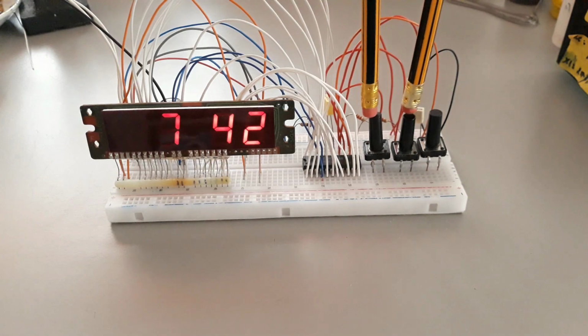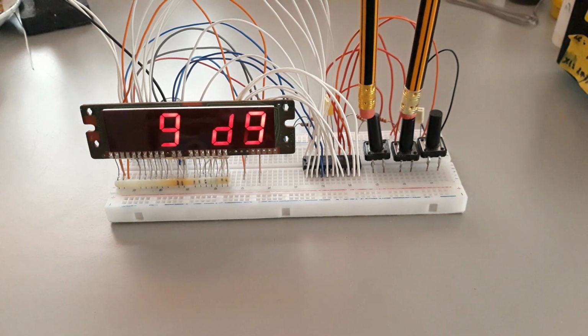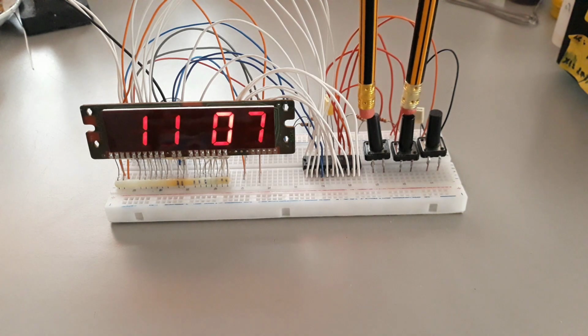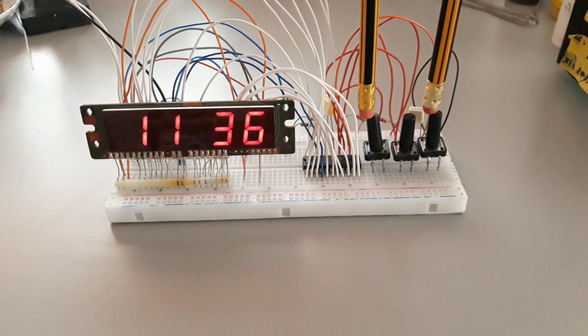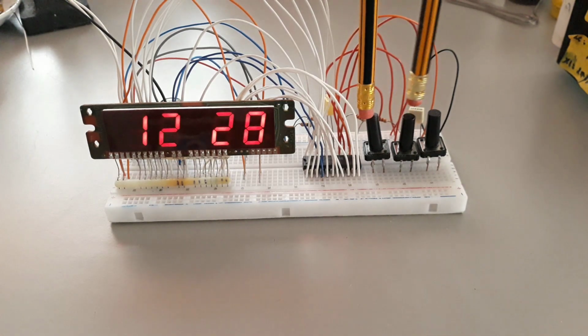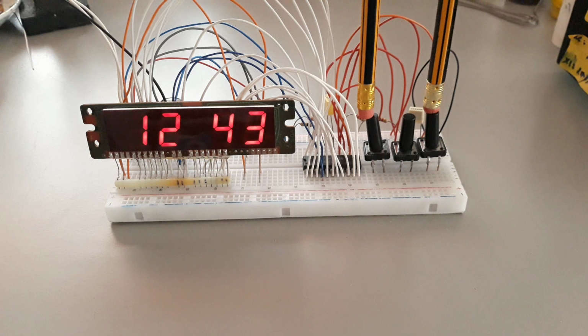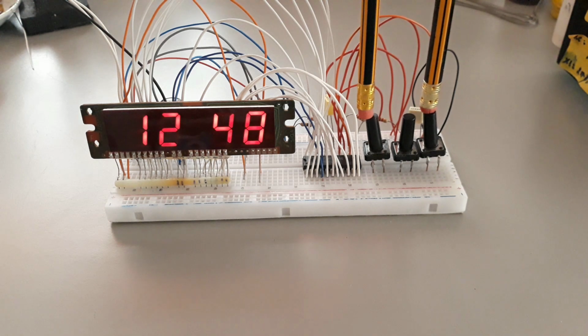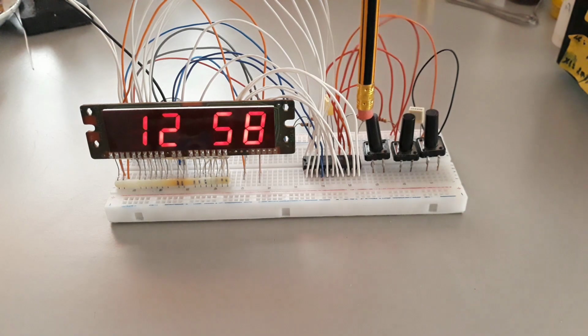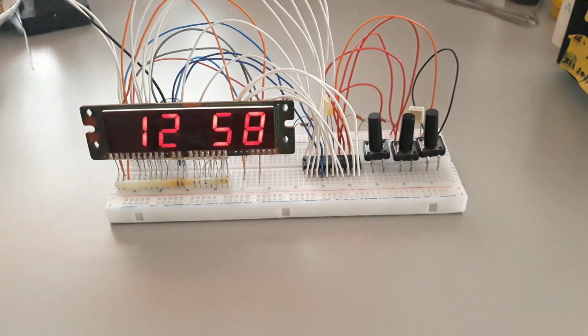Like several of the clock circuits we have already analyzed on the channel, this device displays the time using the format 0:00 rather than 00:00. This detail is important because it means that the fourth digit, the tens of hours digit, only needs to represent the numbers 1 and 2. As expected with a display system synchronized to the mains frequency, the camera captures a visible flicker in the segments. This is normal behavior and is a consequence of the way the display is driven.